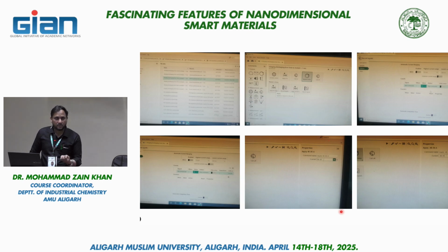If the viscosity is very high, we can paste it easily, but it will not form a uniform coating. And if the viscosity is very low, it will not stick properly. I told you yesterday. In the solvent you put binder, then conductive material and active material, make the paste, and there are certain methods. I explained several methods like screen printed electrode, drop casting, spray coating method yesterday.